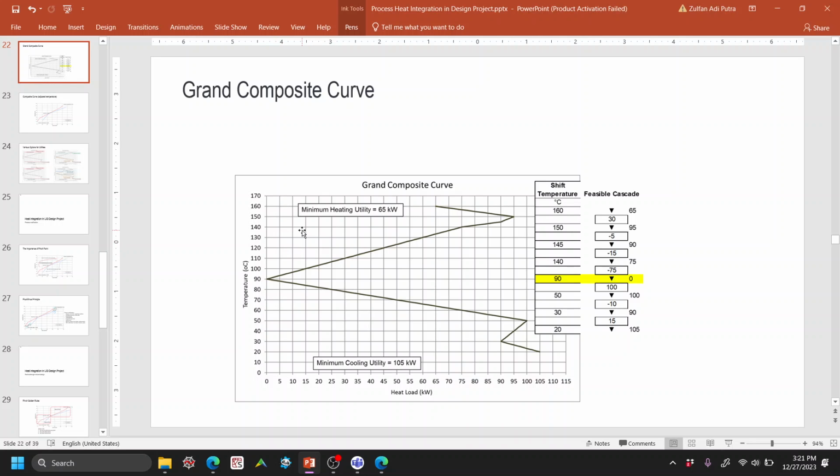You normally see this in a propane propylene splitter. We don't have time to explain what that is, but you can Google this. In a propane propylene splitter, they have this heat pump where they pump heat from a lower pressure to a higher pressure, which they can then condense.